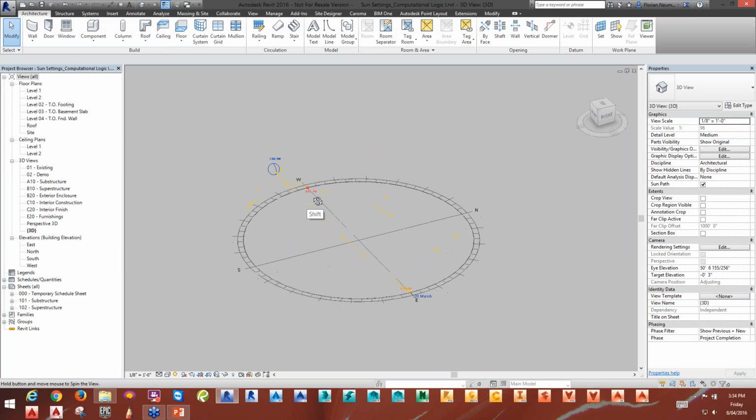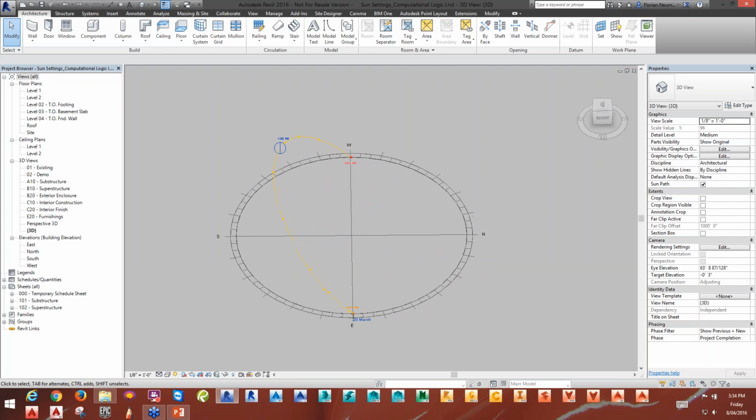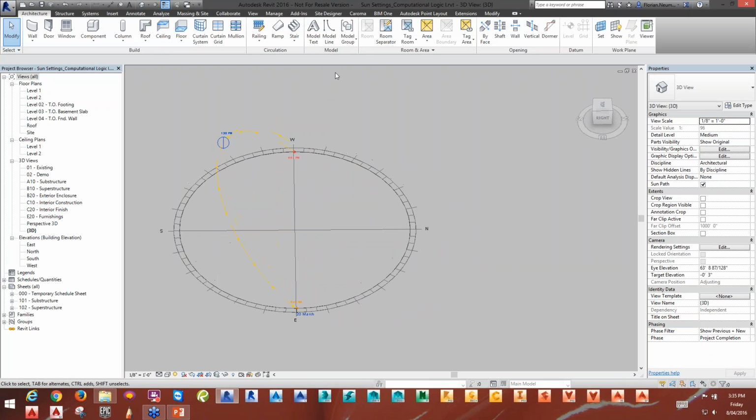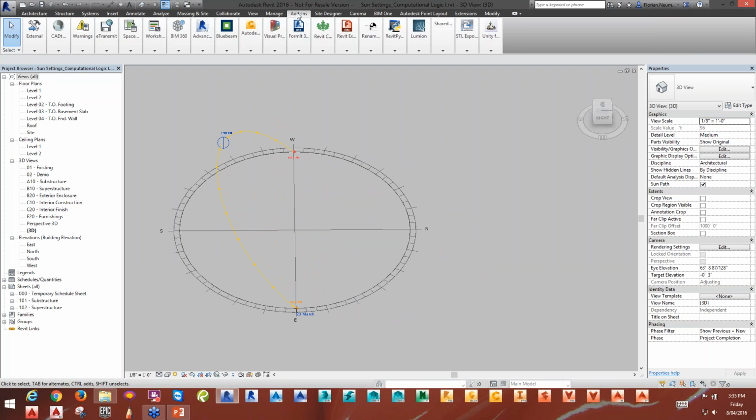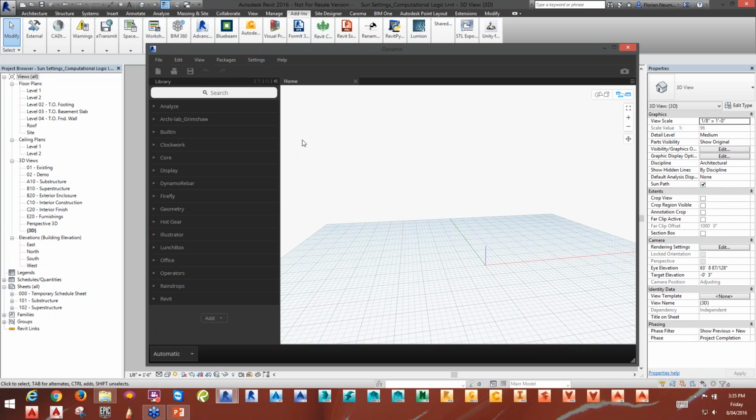So we just prepare a project where we have our sun available, because we want to create some panels that are following the sun. Here as an example, because everybody's always talking about this. So we need to go to our add-ins, and we find here under visual programming our Dynamo. It's still there, just fire it up in a second, and then obviously we need to create something new. So just open up your Dynamo, and then we find here which is new.